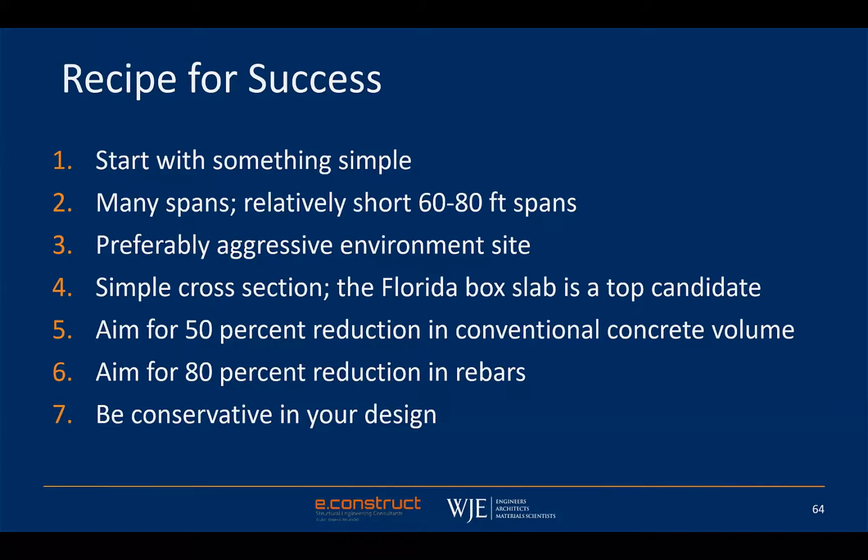Preferably, you can justify your work if you are in an aggressive environment. But even in a non-aggressive environment, it still comes out fairly cost effective. For a simple cross section, the box slab is wonderful. Aim for a 50% reduction in the concrete volume, and for just about 80% or more of the rebar.